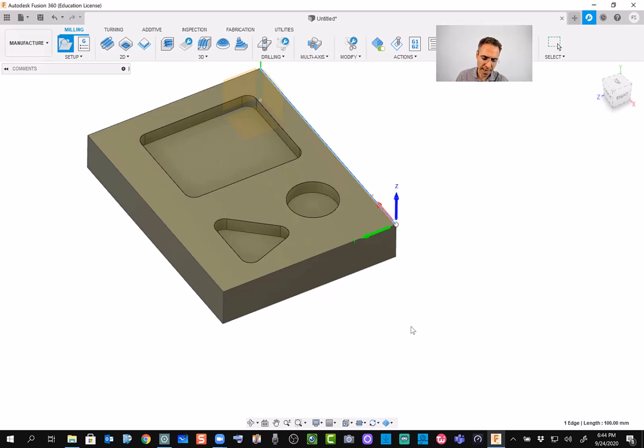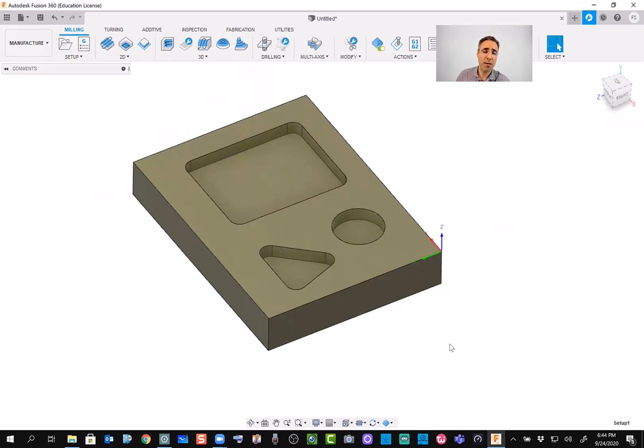All right, so I just click OK. So this is what I have here. I did my setup. By setup, two things that I did: I don't have any extra material to be removed, and also I set my coordinates. I pick a corner because a corner is the best place. Later, when I place these things on the machine, I move my tool and bring it to this point, and I click on the home key and say, this is the 0 point for the tool. Okay. What is the next step?